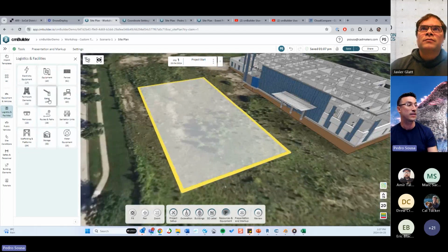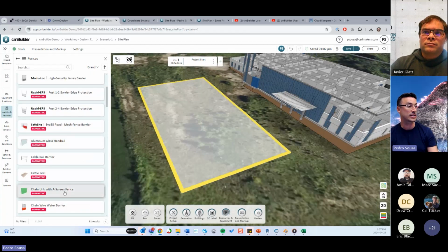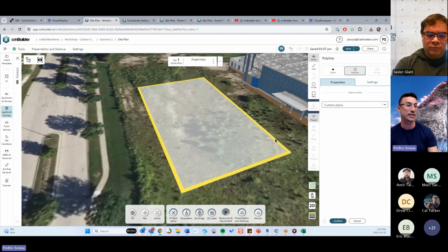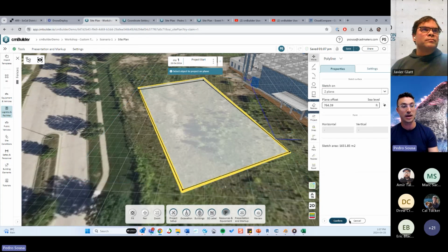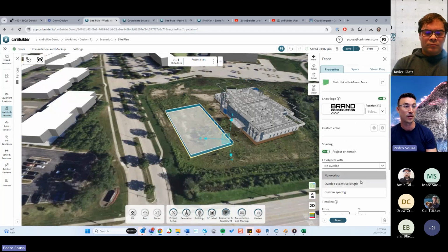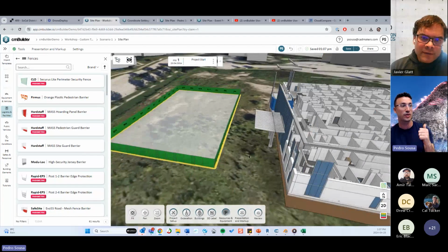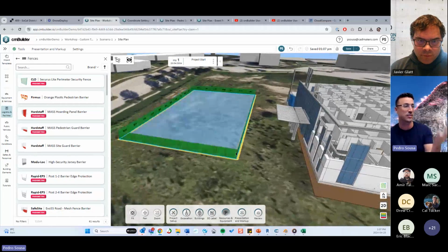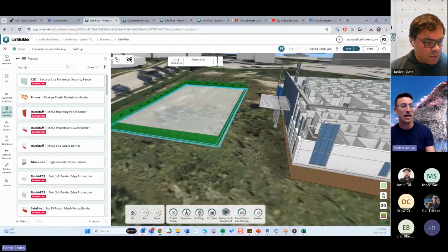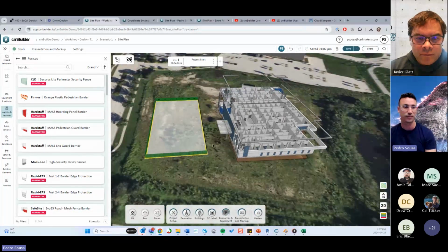So for example, if I'm doing fences over here, I can just go ahead and select any fence, and then click on project, and then go ahead and select an existing shape, confirm, and now I have a fence that is going to be generated on top of that shape. Cool. So you can reuse the sketch from basically any geometry that's controlled by a sketch. So I can reuse the sketch from a fence, from a zone, from a 3D line, and so on and so forth. The only thing that you cannot use for that is the excavation tool.